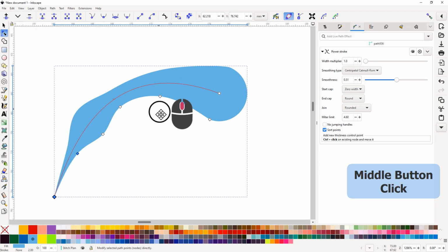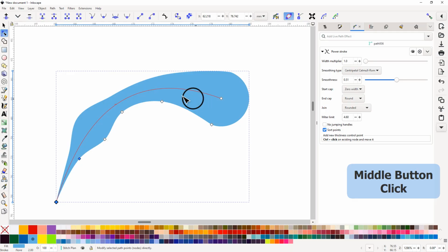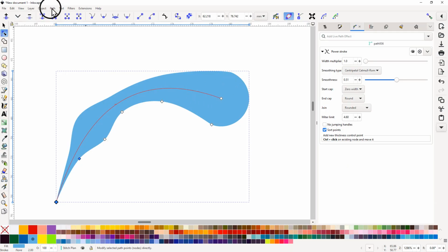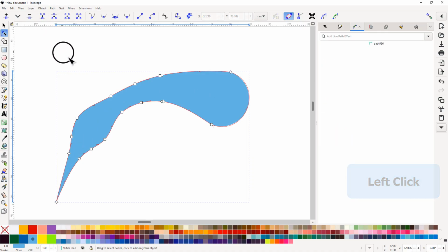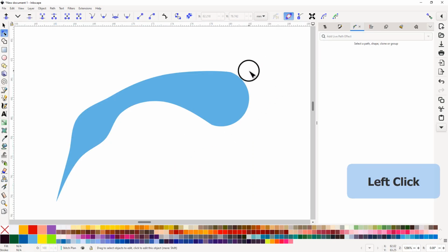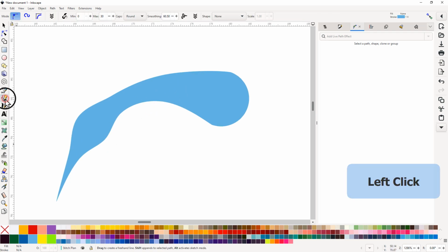And then to convert this one to satin again, the same thing: Path, Object to Path, and here we get a fill on the inside right away. So I don't know why with the other option we did not get a fill on the inside. But now we can go right away to our pen tool or pencil tool, create our rungs,